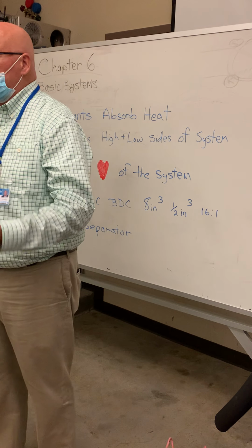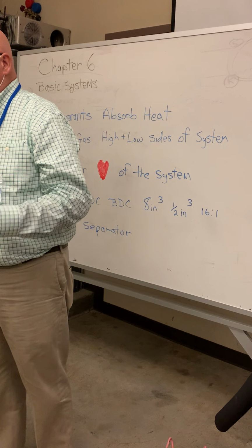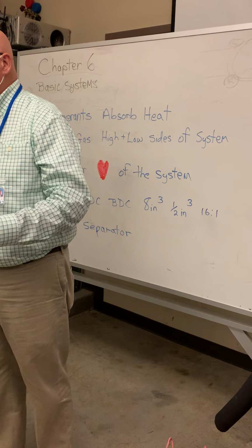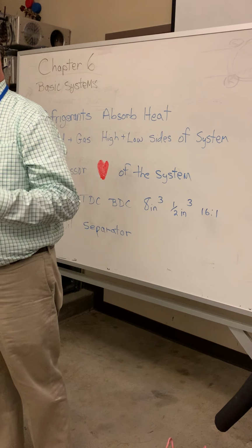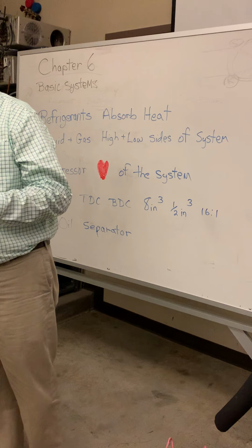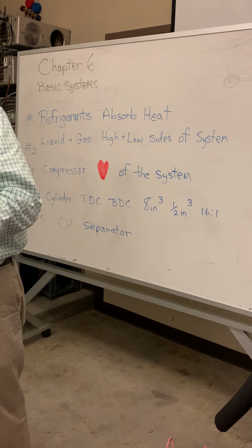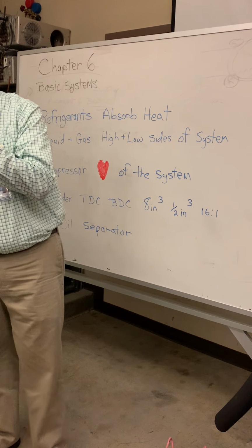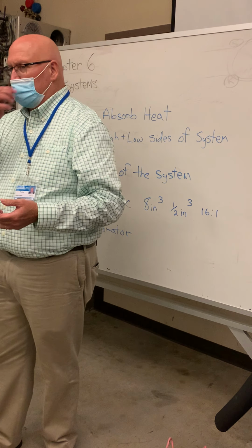And so this can't be emphasized enough. In refrigeration and air conditioning, heat is energy. And so we don't make things cold. What we do is we remove heat from that. The feeling of cold is the absence of heat. Heat is the energy that gets moved from the space where we don't want it to a place where it's okay to be. So the textbook uses this illustration that I actually think they stole from me, because I thought I was the one who started this.